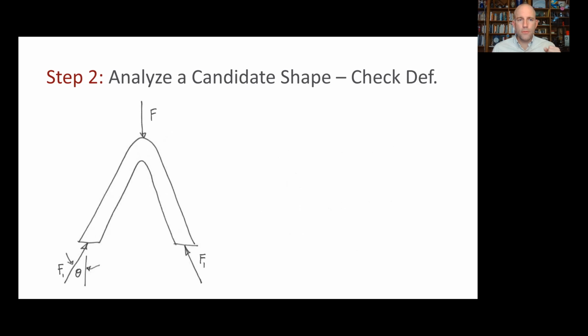What about deformation? So here, what I'd like you to do is draw a sketch of the deformed shape once this load is applied. And then we'll see if that deformed shape is consistent with our assumption about the reaction forces. And the way I like to do this is first think about what's constrained. And in this case, the bottoms of these feet will be fixed. They won't be able to move, and they won't be able to rotate because they're glued to that ground.